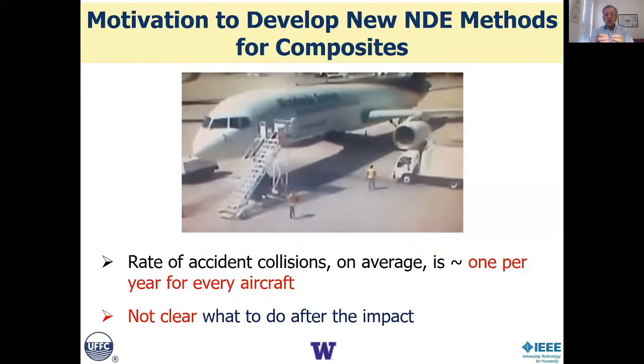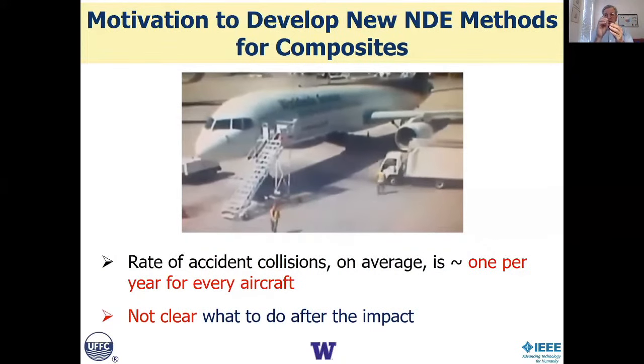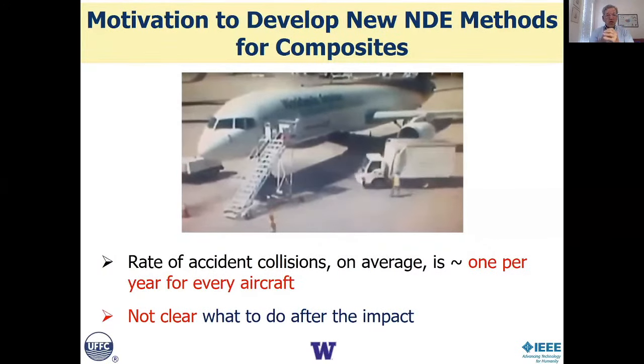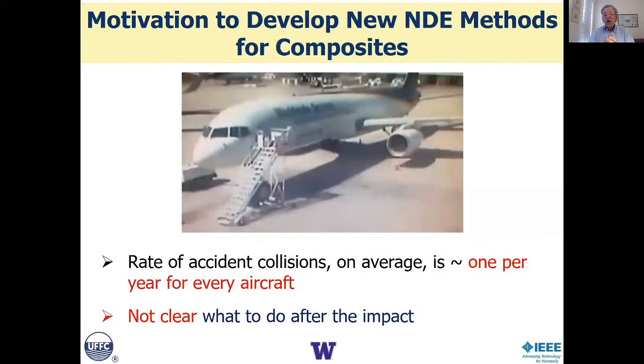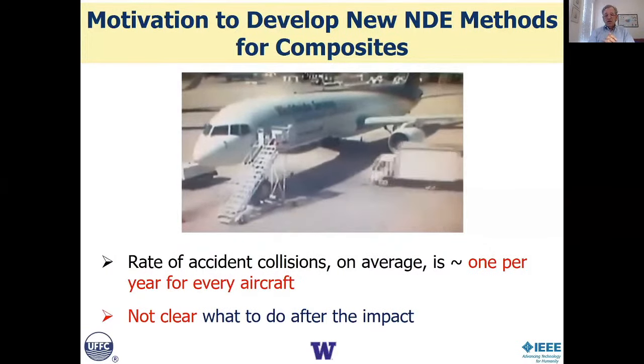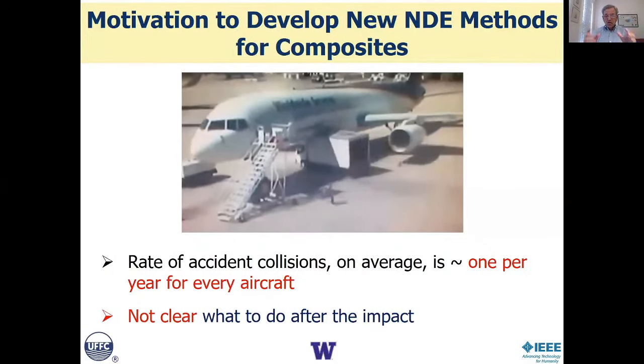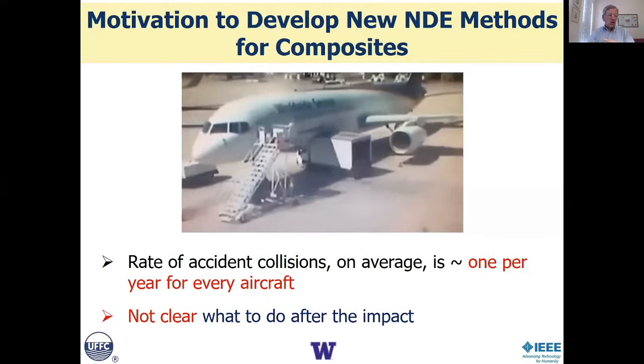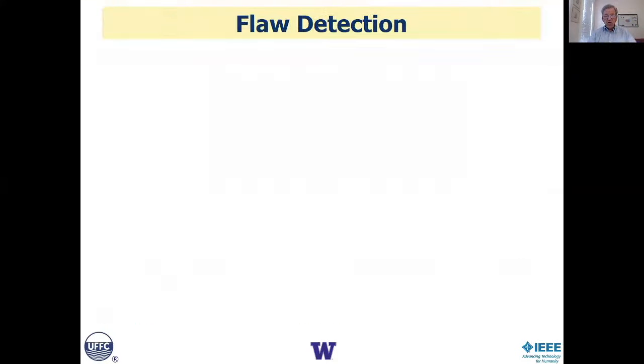When it's metal, you can look at a surface inspection, know pretty well what's happened in the interior. For composites, you don't know. And that's why it's such a great desire to have a non-contact rapid inspection system that can be used in the field. So we've proposed this laser ultrasound system to do that with this double differential Sagnac interferometer.